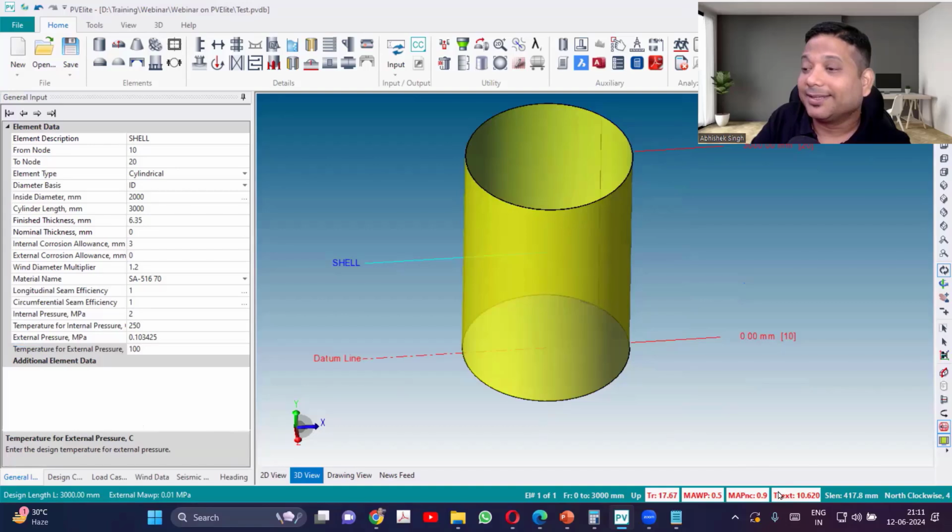Now you can see the thicknesses. What will be the shell length? Shell length is based on the plate width which you are getting. It cannot be more than the plate width which you can get in the market. So that is what you have to take in the model also. Make sense? If you're having a 3-meter width plate, then you can have a length of 3 meters. If you're using 2.4, 2.5, use that. If you're using 1.8 meter width, we'll be using that.